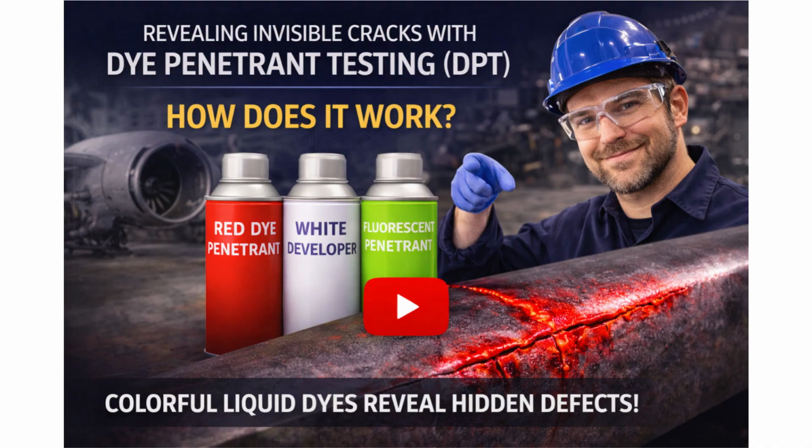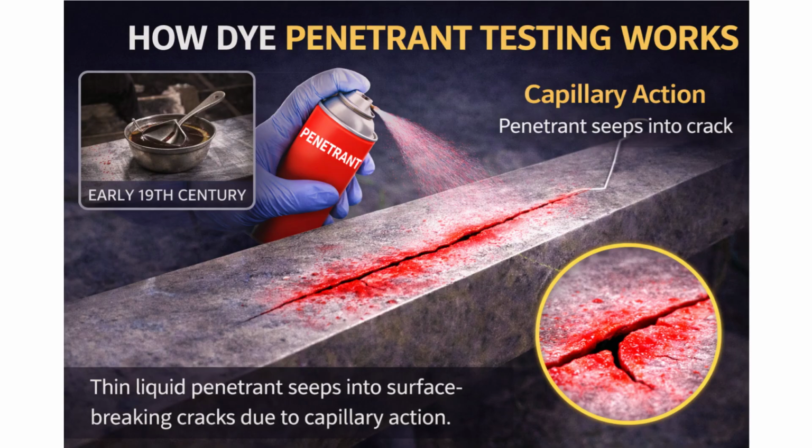So let's get started. Dye penetrant testing is a non-destructive testing method that uses liquid applied to surfaces to identify surface breaking defects in non-porous materials. But what does that actually mean? Let me break it down for you. DPT is one of the oldest and simplest NDT methods, with its earliest versions using kerosene and oil mixtures dating back to the 19th century.